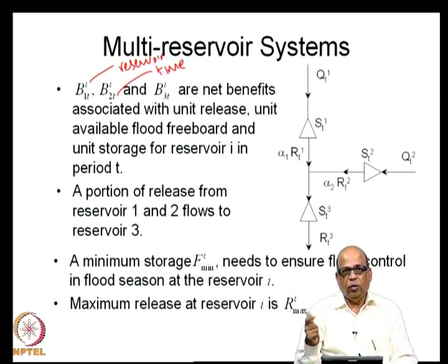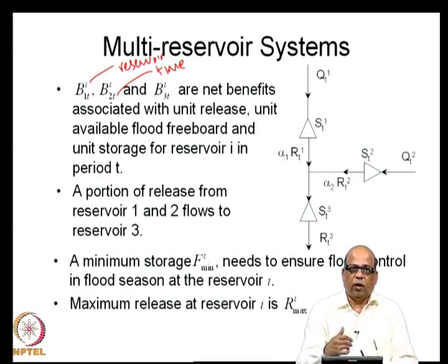Associated with unit release, you have the benefits from each of the reservoirs. Associated with the flood freeboard that you maintain during the flood season, you have a benefit, associated with unit flood storage that you maintain, you have a benefit. Associated with the storage, because of the hydropower, you have benefit at each of the reservoirs. Now, these benefits need not be always economic benefits, they can be intangible benefits, they can be physical quantities and so on. But right now you just assume that they are returns, or something good that happens because of these particular variables like release, storage, flood control storage and so on.